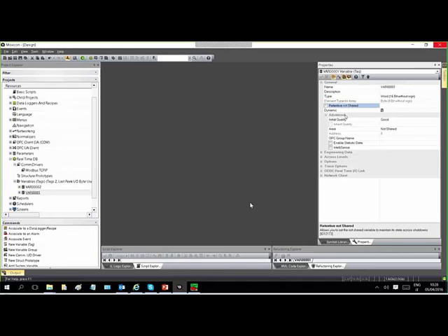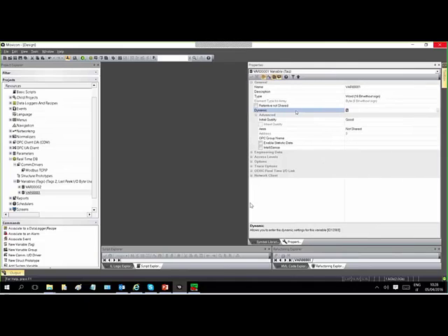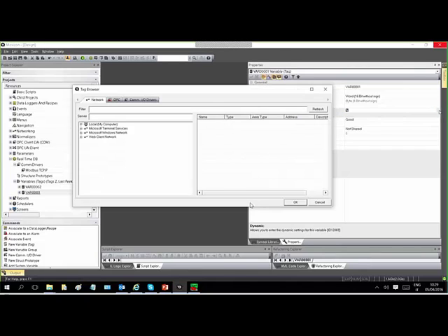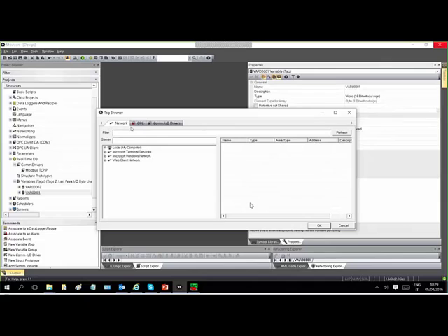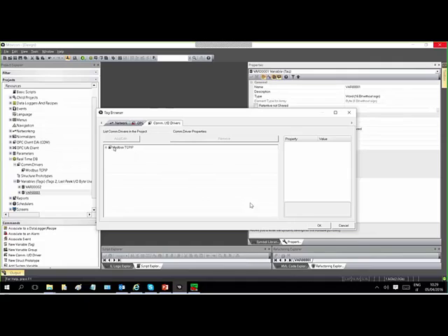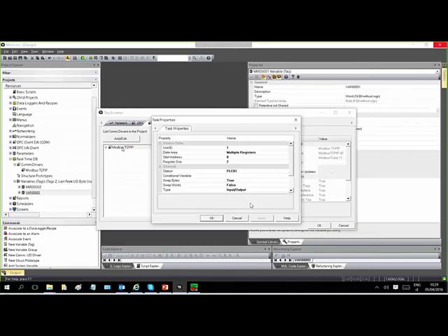Retentive not shared allows you to set the not shared variable to maintain the state of the variable across the shutdown. Here is important, and is what I want to focus on now, because it's in relation with our driver. You can build the communication with the PC manually also from here, if you cannot import. How? Simply, this variable must be associated not with the PC, but with the communication driver. Which driver? With my Modbus TCP/IP driver.